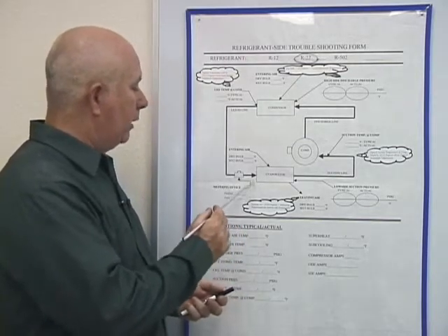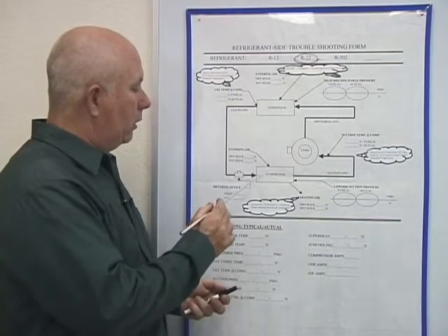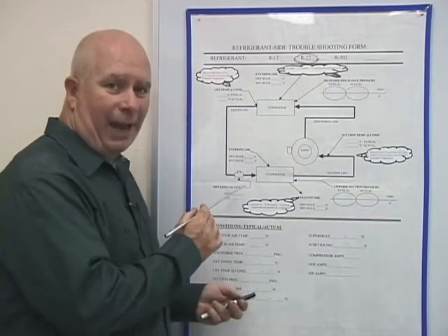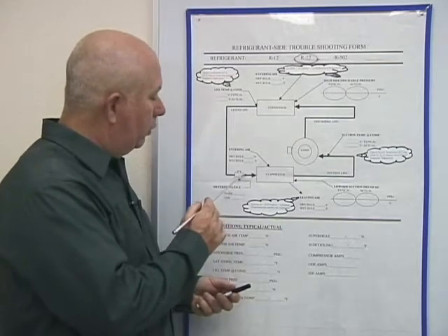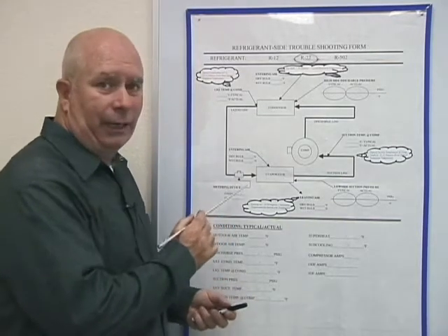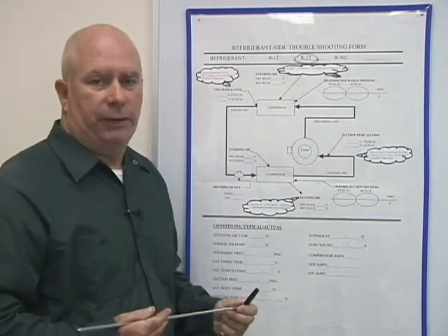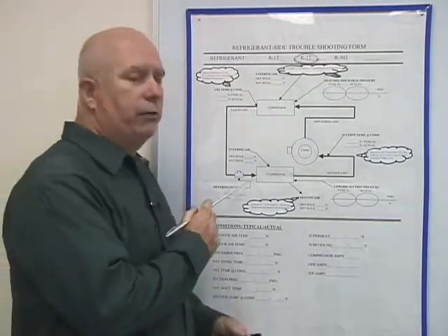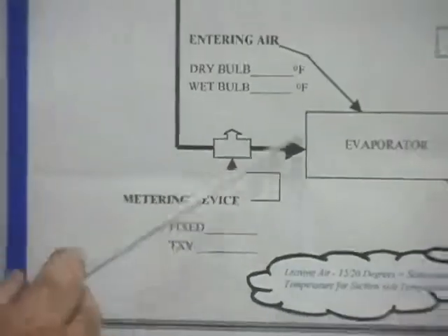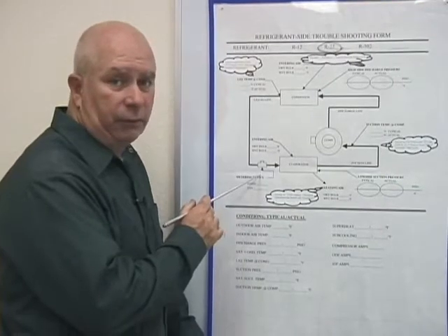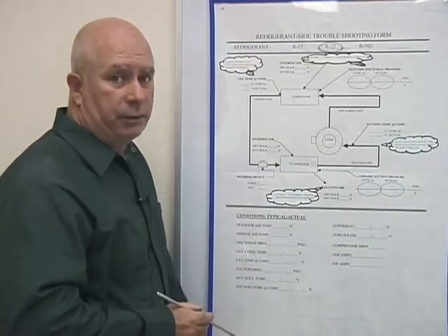So understand the metering device, if it's not physically visible 4 to 6 inches back, you're going to know at least somewhere in that line at the manufacturer they put a metering device in there. And the reason they do that is because it's more economical and cheaper in the long run than to put the TXV. That's how they cut down on the prices.